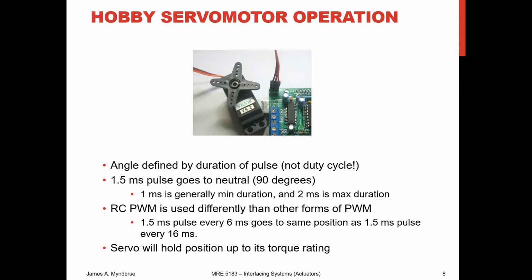So when you're using servo motors, you got to be a little careful about these torque ratings, and the limiting factor is usually the plastic gears or the metal gears, and obviously you're going to pay more for the metal gears. So be a little careful in terms of using servo motors to make sure that you're using them appropriately.